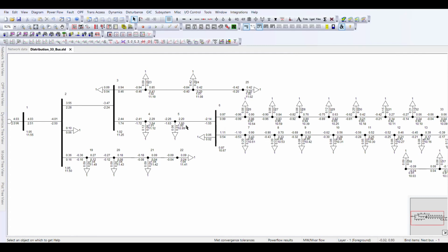We are going to monitor the flow on each and every section within this system, and once any one of the sections gets overloaded, we are going to stop our simulation there. So we will attach a random distributed generation on a random node, run, and identify if there is any overloading.